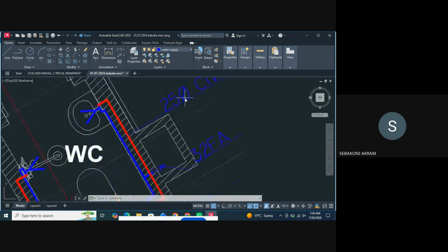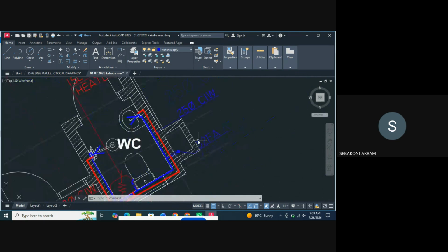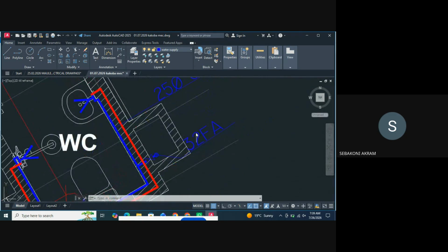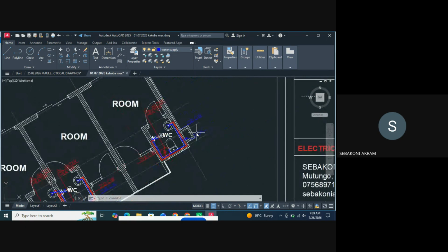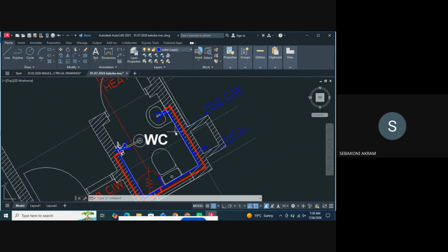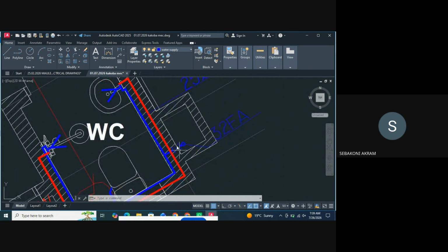Now, usually this pipe is 25. This one is 32 because it might be supplying even other fixtures above this. That is one of the reasons. Another reason could be when this flow is really so far down. Now when it is far down, also the pressure would what? Matter. So I would want you to really, I don't want to go into those calculations.